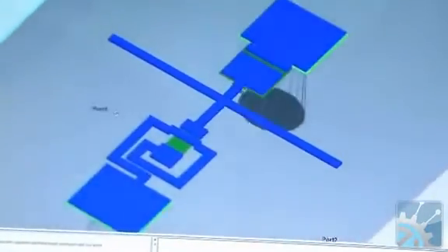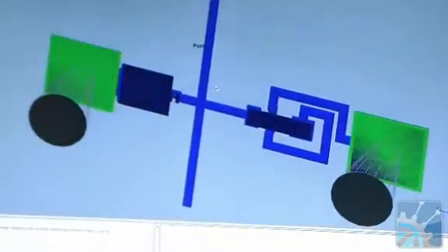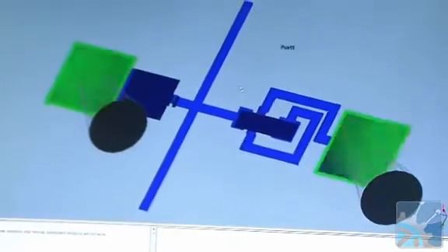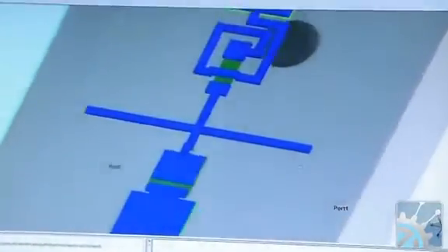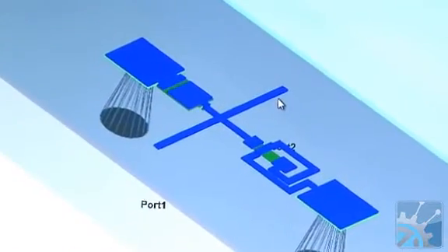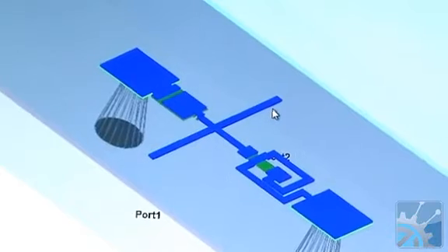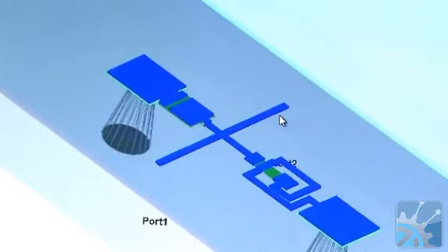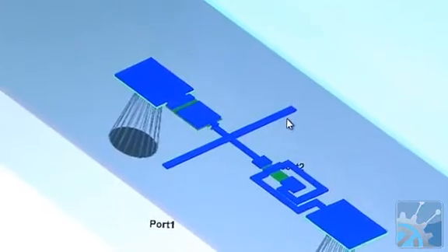This framework, built in ANSYS Designer, allows an engineer to set up a layout-based design. They can also import it from CAD tools such as Cadence or Mentor, and easily set up the excitations, the simulation, and everything, and solve directly from the designer interface with the HFSS solution engine. So it's a really easy entry point for engineers who are comfortable working in layout and want the accuracy and rigor of HFSS.